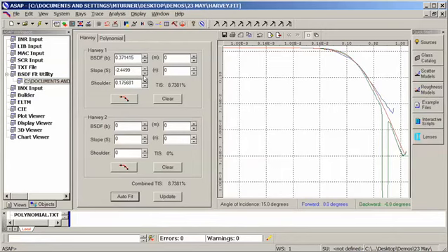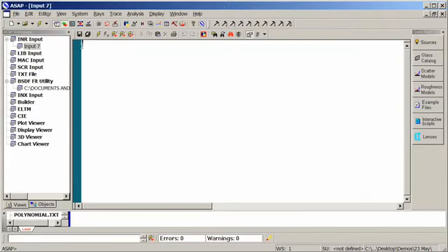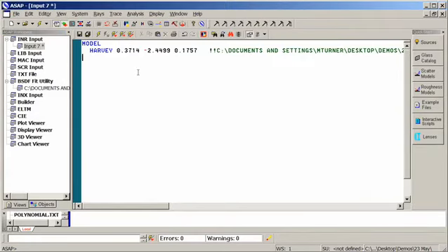I'm going to accept this fit, and say I wanted to use it within my ASAP file. I'd come over here and copy this data, which will copy it basically to the clipboard. I'm going to open up a new file and simply paste. And what I have is the information about the Harvey model, including the fact that it is the Harvey type scatter, and these are my 3 Harvey parameters. I'm now free to apply this model to any surface in my system that requires optical scatter.